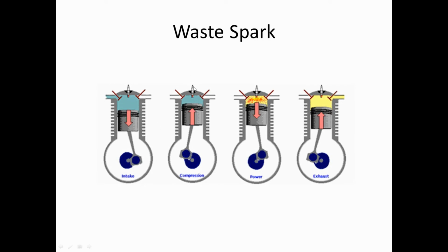Obviously we want it to fire at the top of the compression stroke, which drives it down for power. Firing the coil in the middle of the power stroke or in the exhaust stroke does nothing. Now, pay attention to this because this is very important.